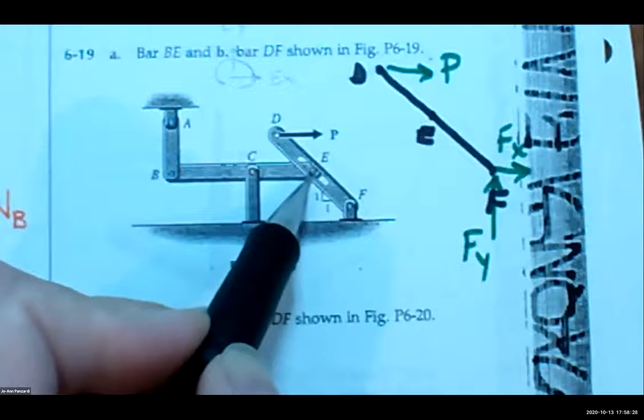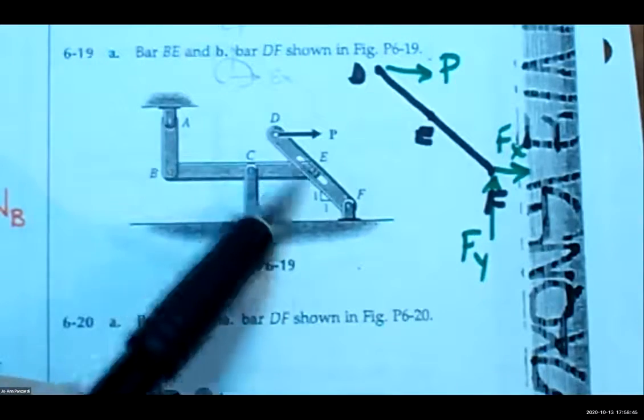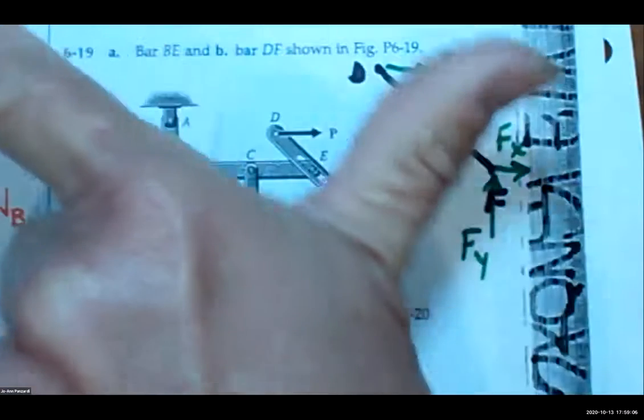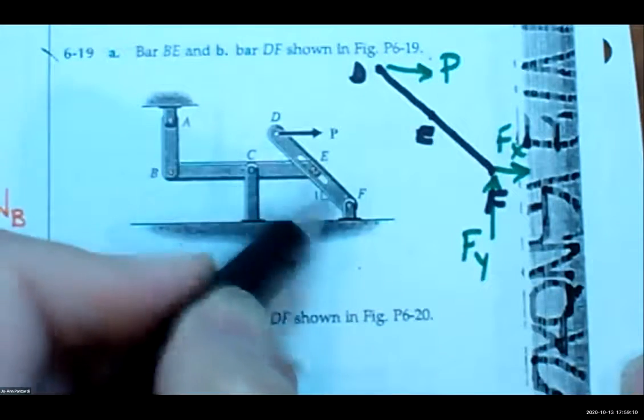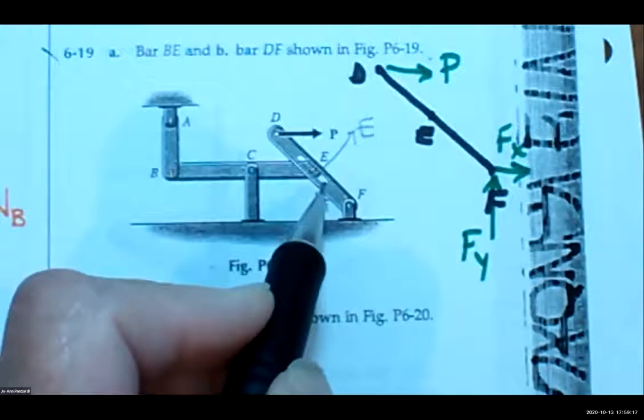This rod could move in here. So if you look at these two rods relative to each other, so if you had an erector set, you had a rod and another rod, and there was a slot in here, can these rods move relative to each other in this direction, Tim? Yes. So that means it does not resist it, so there's no reaction that way. What about in this direction? Can they resist motion in this direction? They can resist motion. So even though I started drawing out my force in the X and force in the Y, I could rotate my axes. And I know that they could move relative to each other this way. So there's really only a force going this way. And then what about, can they rotate in here?